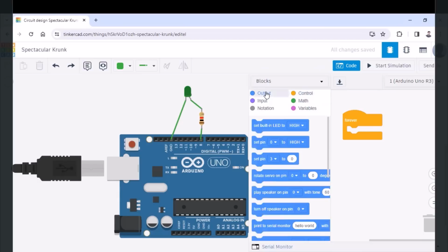Now what I want to do is give input to my LED, and I want to send 1 or 0. As we studied earlier about signals, we are going to transmit digital signals, and pin number 8 is the digital pin where I want to give some value.